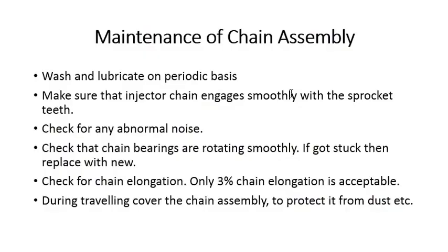Check that chain bearings are rotating smoothly. If stuck, then replace with a new one, because if we do not replace the bearing, then ultimately the load will be shifted to the other bearings and then these bearings will break and there may be a problem in the job. Check for chain elongation. Only 3% chain elongation is acceptable.